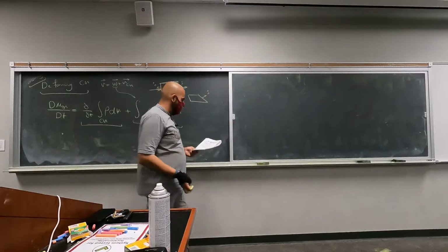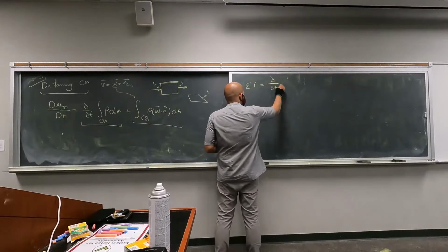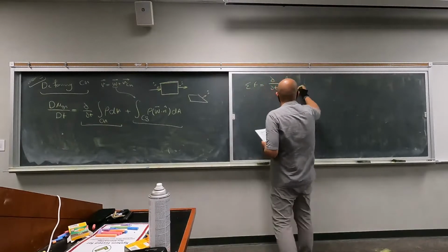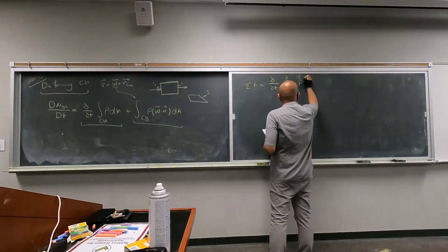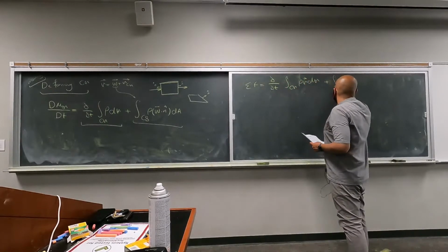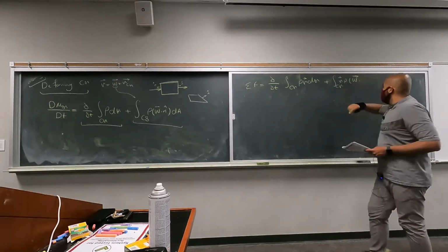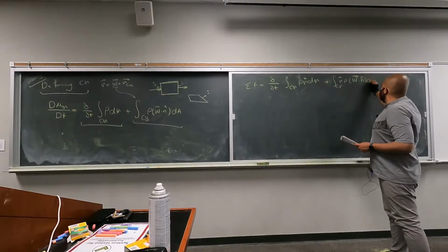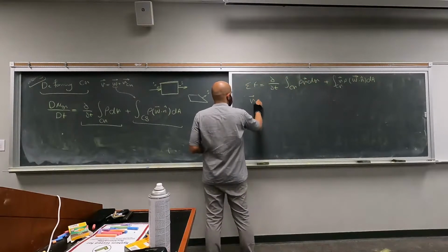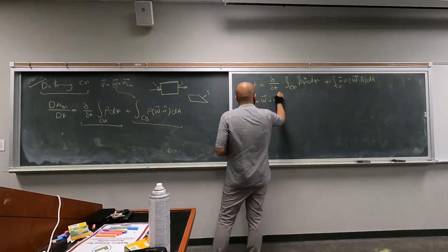And you will eventually end up with sigma F equal to the change of linear momentum inside the control volume plus, and here's the difference, your velocity in that specific direction, W instead of V. And W can be calculated using this equation.